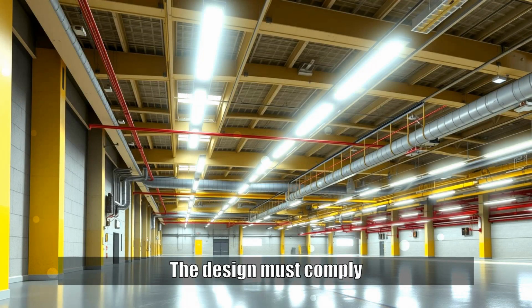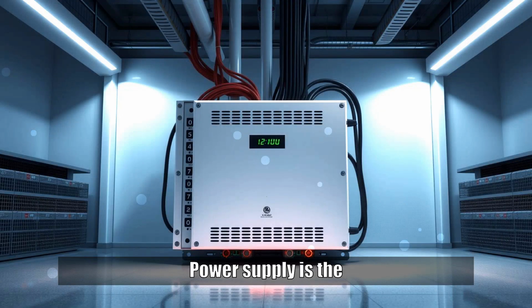The design must comply with standards such as NFPA 72 and local building codes, ensuring sufficient sound pressure levels and light intensity throughout the facility. Power supply is the final pillar of a fire alarm system.